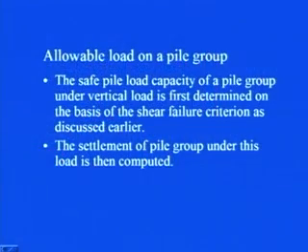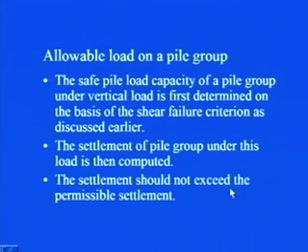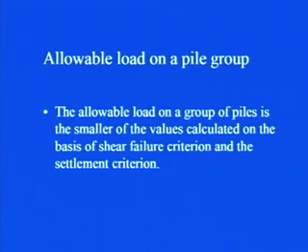Then the settlement of the pile group under this load is computed. You know how you can calculate the settlement. Depending on this safe pile load capacity, whatever that load is, you can find the corresponding settlement of the pile group. Obviously, the settlement should not exceed the permissible settlement, because from the serviceability point of view the settlement has always to be less than the permissible settlement.